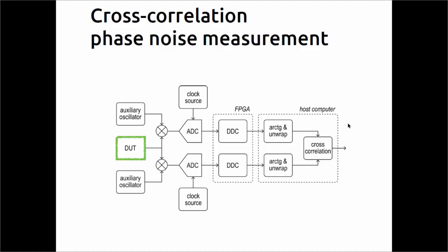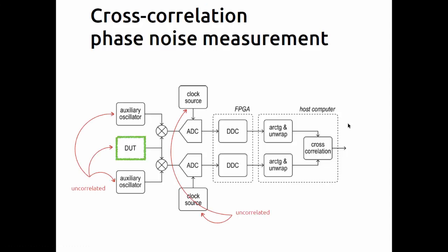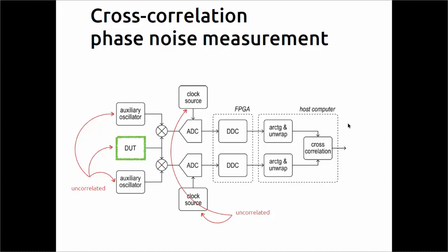And we have two almost identical systems that I use to derive two heterodyne beat notes that are then sampled and processed, which I will describe later. The important thing here is that those three systems need to be completely uncorrelated. All three are different combs locked to three different optical cavities, and the signal generated by the mixing of those three needs to be sampled with uncorrelated clocks.